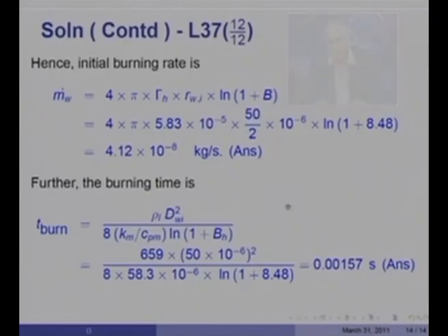So, what we have learned from these sets of problems is that in general, in air-water evaporation problems, B is very small, but when fuels evaporate, B can be substantially bigger than 1, of the order of 2 or 3 or something of that kind. When the fuel burns, it would be of the order of 8 to 10 or even a little greater than 10 in a variety of different liquid fuels. But all this is done in stagnant surroundings.